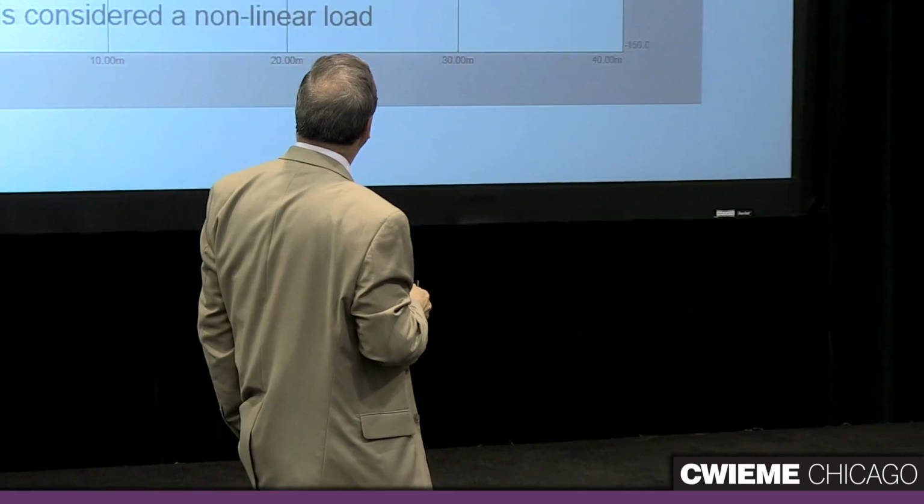device. But suppose I have this other piece of equipment hooked up to this transformer. It's drawing currents that look like this. Well, we know 2 things about this piece of equipment. First, because the current does not look like a sine wave, right? That's definitely not a sine wave. Therefore, we would say that that waveform has harmonics. It contains harmonics. And we would call this a nonlinear device.